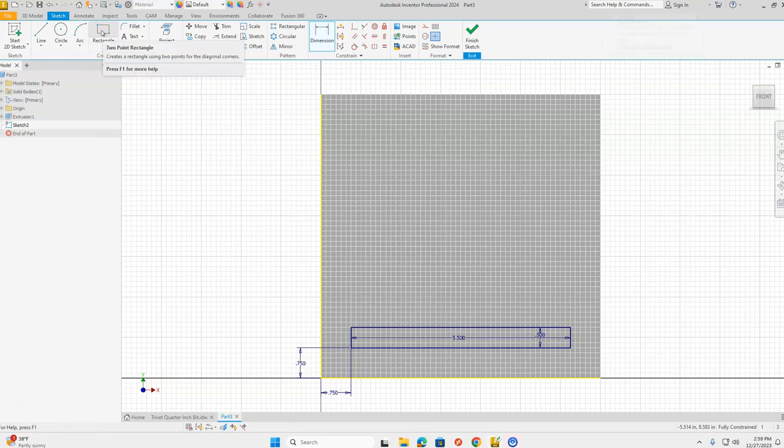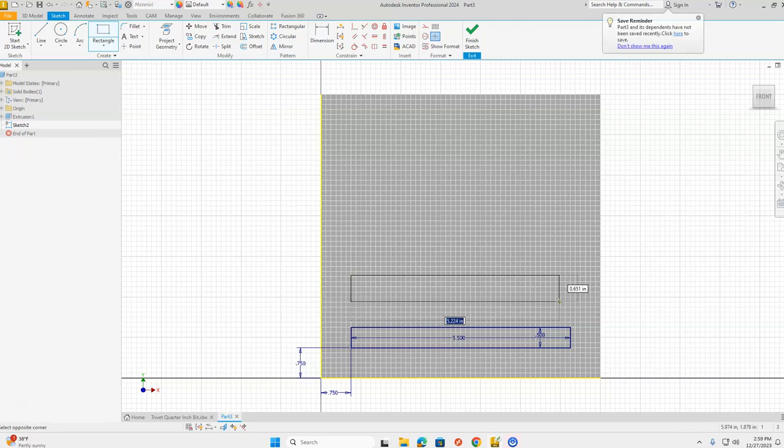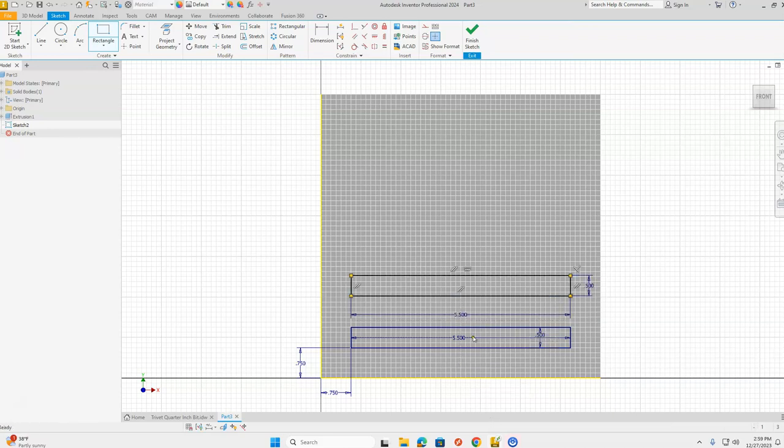It's going good. Let's try our next couple rectangles. Rectangle tool again. Stretch this rectangle out. For the horizontal dimension, 5.5 is what we're typing in. Press Tab. For our vertical dimension, 0.5. Enter on the keyboard. Once again, we're going to press the Escape key on the keyboard, and we're going to push our dimensions for this box inside of that box to reduce the clutter on the workpiece.